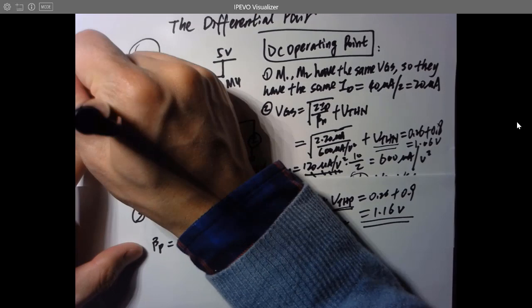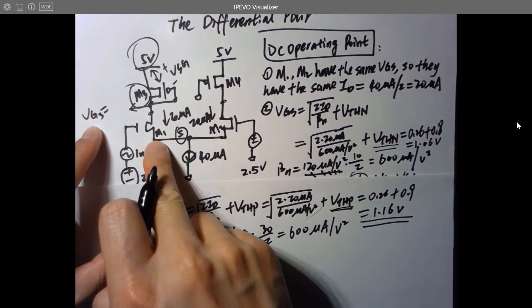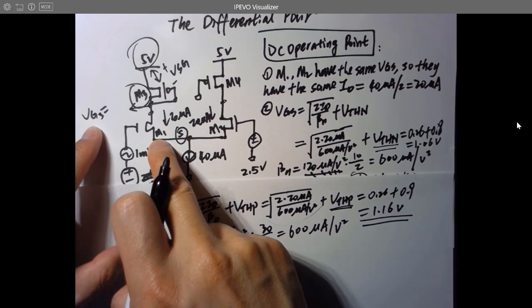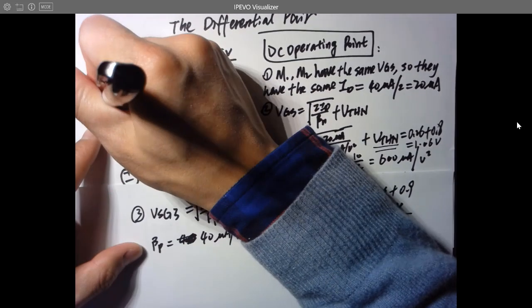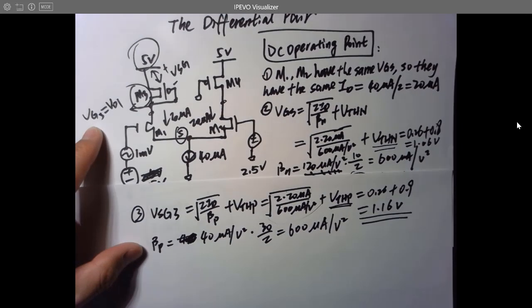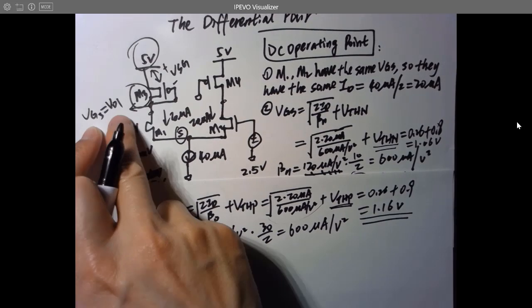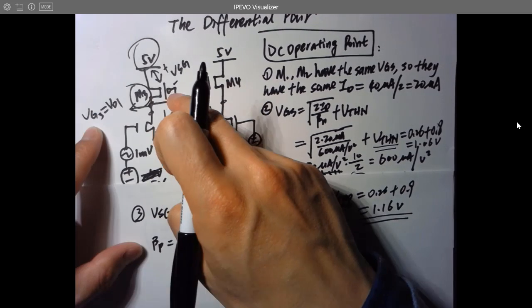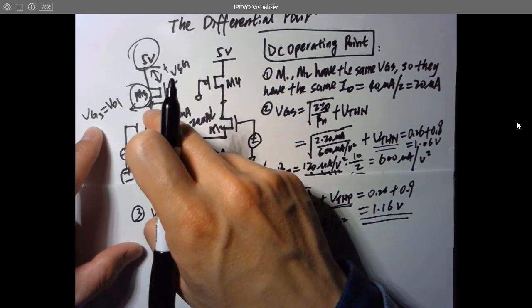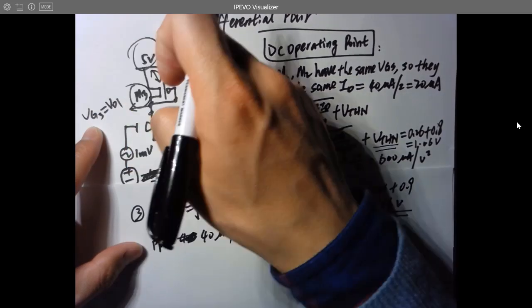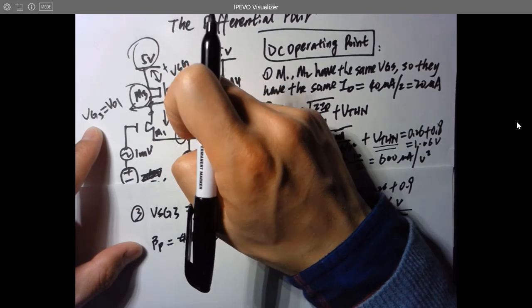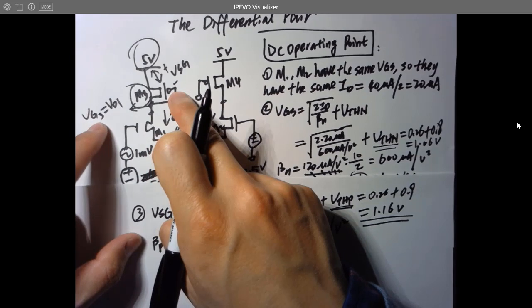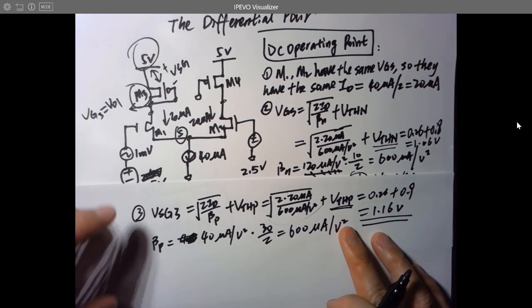And also the same point equals the drain voltage of the first NMOS transistor M1. So this equals VD1, right? So the drain voltage of M1 is the same as the gate voltage of M3. This is being shorted together. Since we know VS, we know VSG, so definitely we can get VG3. So we will know VD1 as well.